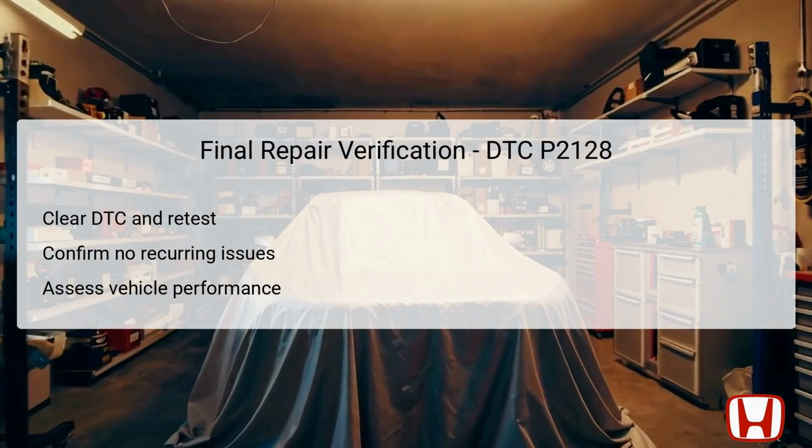After completing the necessary repairs following the troubleshooting steps, conduct a final verification to ensure the issue is fully resolved. Start by clearing the diagnostic trouble codes, DTCs, from the vehicle system to reset any stored errors. Following this, retest the vehicle under usual operating conditions to confirm that the DTC P2128 does not recur.